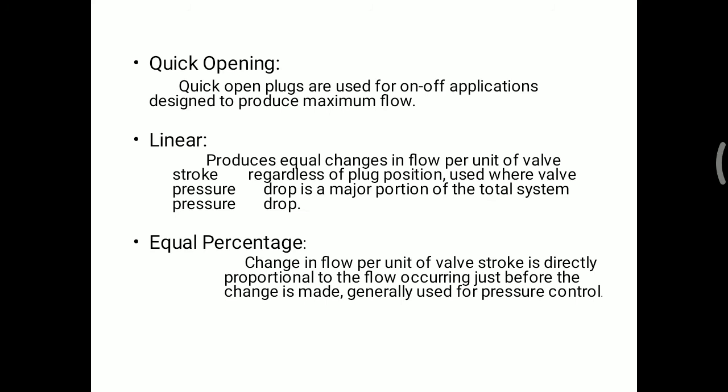The quick opening plug quickly opens, giving the quick opening characteristics. Quick open plugs are used for on-off application designed to produce maximum flow.